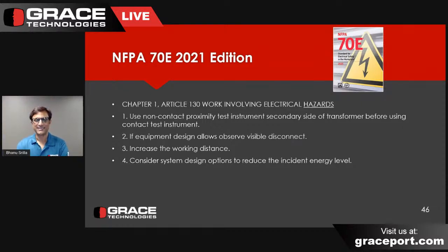Right. So if you were told by NFPA or someone else that wearing a 100 cal or 140 cal suit is dangerous, it's not going to protect you because the blast pressure is going to be high, it was false. And if you want to talk about this one, I'll gladly. For a decade, I've been telling everybody arc blast pressure is not what it's been made out to be.